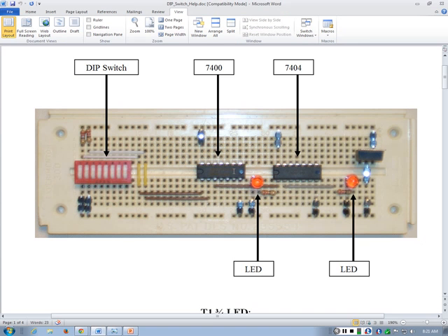At the top of 1, we are basically shorting this 1 to the VCC, because this is the row for the VCC. Now how is it a row for the VCC? Because we always keep this row for the VCC, and we always keep the last row, because you know, this row is shorted, right? The top one, the row is shorted. The whole row is a single point basically, okay? And the bottom row is a single row. So what we do is, we use the top row for the 5 volts.